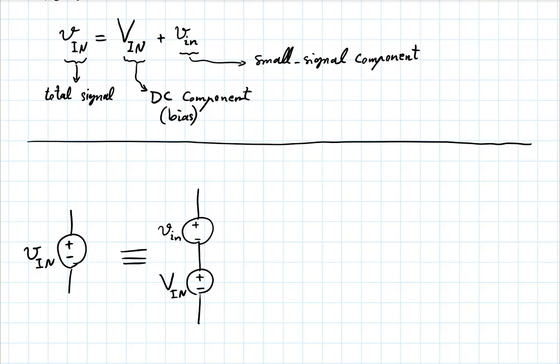In general, you cannot apply superposition to BJT and MOSFET circuits because they're not linear elements. But if you're making very small changes, you approximate them as linear elements for the purpose of that change. And that's why you can look at the response to that small change on top of the response for the